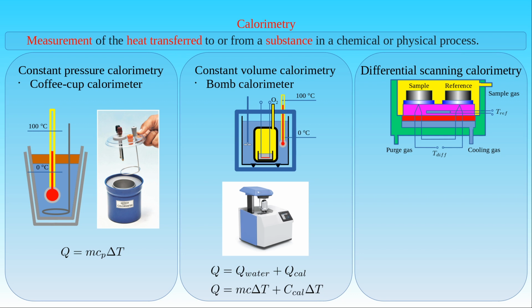Heat is supplied into the sample and the reference through the heat sink and the heat resistor of the heater, where the heating has a controlled rate determined by the reference temperature T-ref. Heat flow is proportional to the heat difference of the heat sink and the holders. When endothermic or exothermic phenomena occur in a reaction or transition, heat is compensated by the heat sink. The oven is purged with the sample gas, so that transitions and chemical reactions in different atmospheres can be examined. Different purge gases can also be used in the experiments, for example air providing an oxidative environment, and nitrogen providing an inert environment.